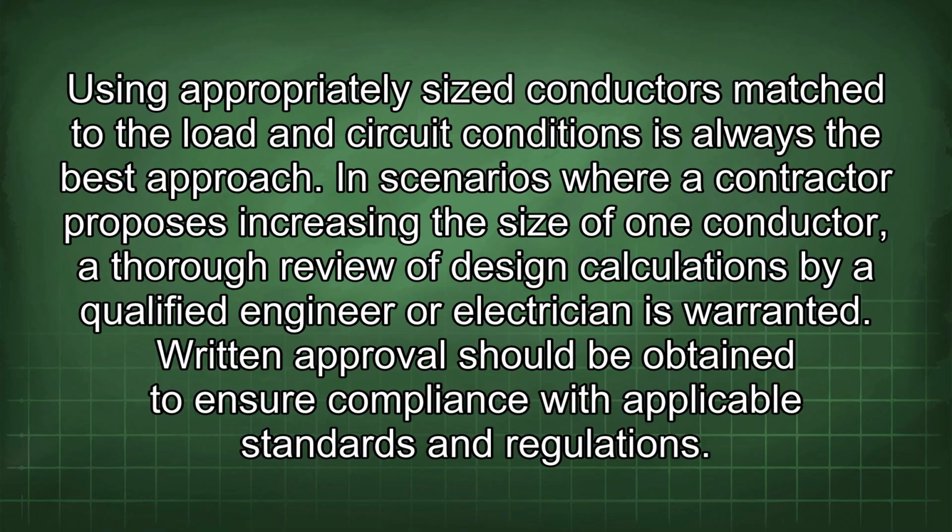In scenarios where a contractor proposes increasing the size of one conductor, a thorough review of design calculations by a qualified engineer or electrician is warranted. Written approval should be obtained to ensure compliance with applicable standards and regulations.